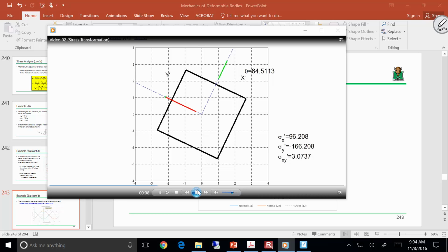You know, P over A, that's simple. You know, T over J, that's simple. We developed a coordinate system that made sense, but it was arbitrary. We just said, okay, the x-axis goes that way because it made our math easier. But what we really care about is that worst-case scenario. In other words, the principal orientation. All right? Make sense? Okay.